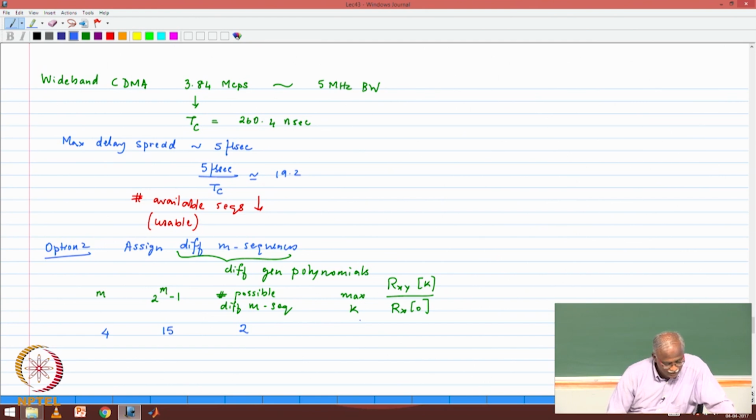That is not the biggest factor. The cross correlation actually is quite high, 0.6. What would it have been had it been an M sequence? It would have been 1 over 15. So basically, had you used sequences from within one M sequence family, it would have been 0.067. Okay, so it would have been actually a very good system, but this stupid multipath ruined the whole thing.